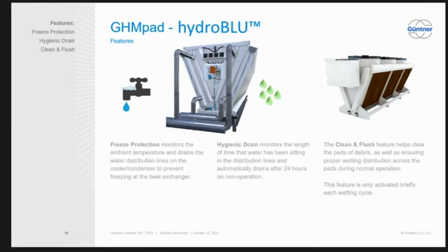No, and the reason we don't do that in the controls, I'm sure you've seen it, there's a lot of guys that know just enough to be dangerous. If you get a guy out there that's just messing around with it for starting it up and puts it in manual mode and overrides it, and forgets to turn it off, then it freezes. The weather gets below freezing and cracks the distribution lines. That's a much more expensive fix.